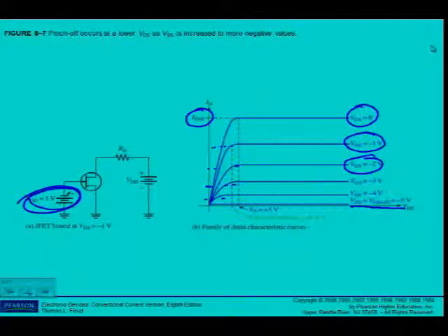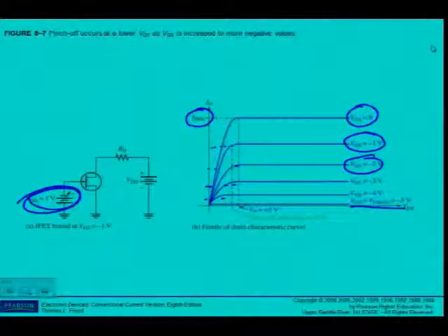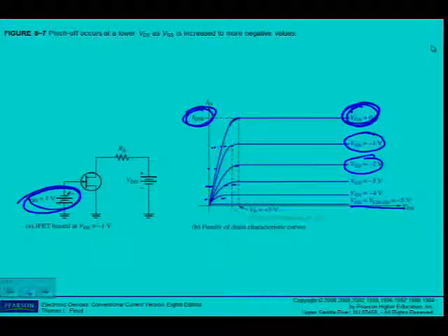The term pinch off is not the same as pinch off voltage. You must be very clear on this. If we go and look at this graph, where did we find V pinch off? V pinch off, we determine where VGS was equal to 0, and I've got my maximum current, so that was point B on the previous graph, né? There, that point B, just as it starts to become constant, I get a value. In this example, let's say V pinch off is equal to plus 5 volts.